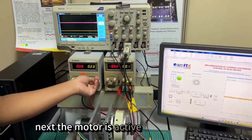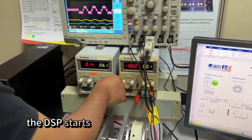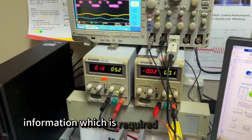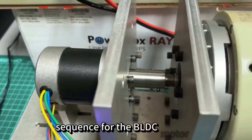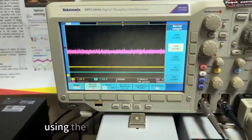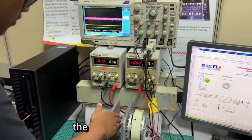Next, the motor is activated using the start and stop control in the Simulink interface. When the enable button is turned on, the DSP starts reading the Hall sensor and current sensor feedback. The Hall sensor provides rotor position information, which is required to determine the correct commutation sequence for the BLDC motor. At the same time, the reference current can be adjusted using the control code in Simulink. This reference current becomes the target value of the hysteresis current control.